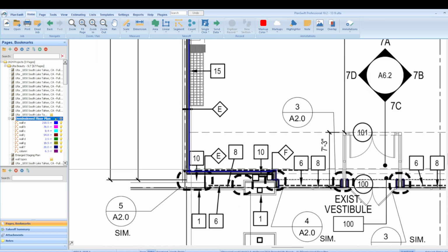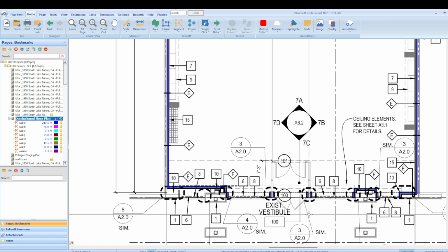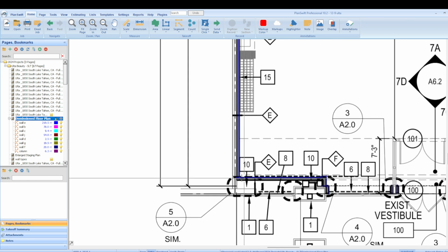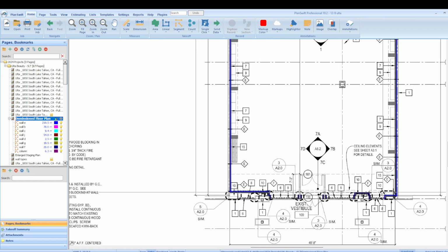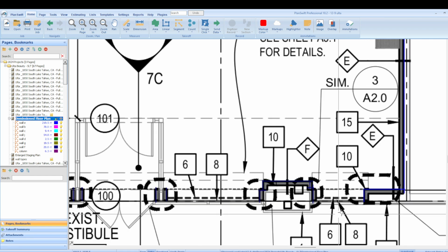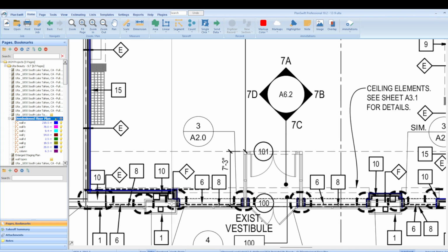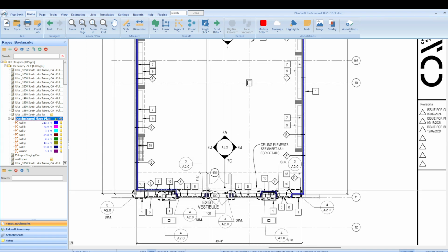This is a detail call out. So this is telling me that whatever's in that circle, I'm going to go to that picture on that page, and it's going to tell me what I should do. And similar means I'm going to do the same thing on the other side. Okay, the same thing that I'm doing over here, because it's similar, I'm going to do it over there. Okay, and then these are broken out a little different. The similar part most probably is associated with the things that are the same, like these circles are the same. Okay, that's the same, that's the same.